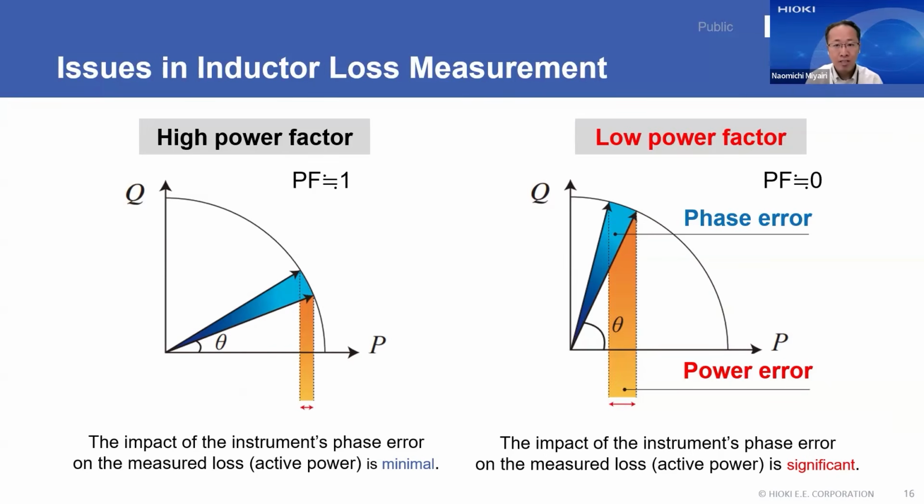Now this is especially relevant for inductor power measurements. Because the power factor of an inductor is nearly 0, the phase angle sits very close to 90 degrees. This means that phase accuracy at high frequencies, including the switching frequency, is the single most important specification to look for in your measuring setup.